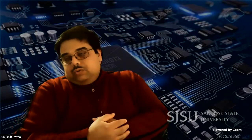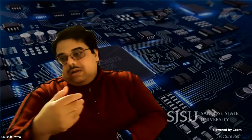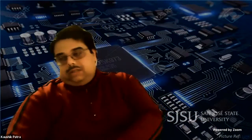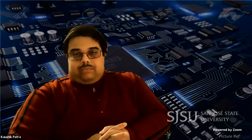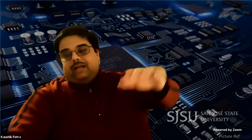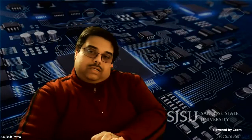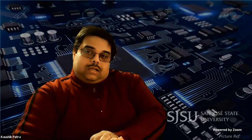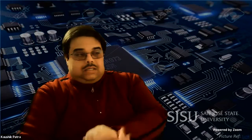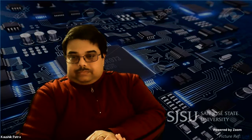From that, it should be easy enough: if this is my opcode, this is the action I need to do during the instruction fetch, decode, or execute. It's a huge series of if-then-else or switch-case blocks, whatever way you want to implement it in Verilog. But the bottom line is that it's a chain of if-then-else statements.